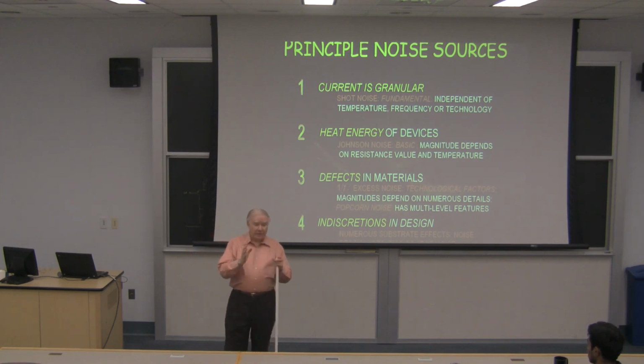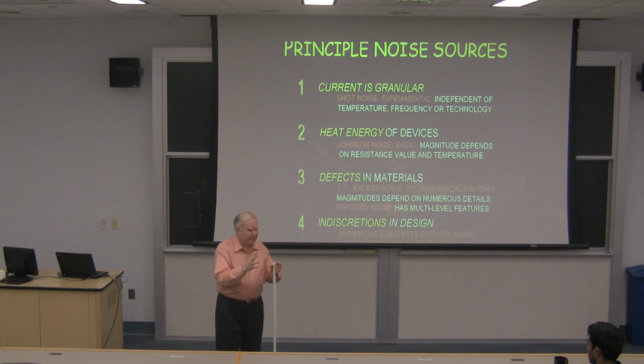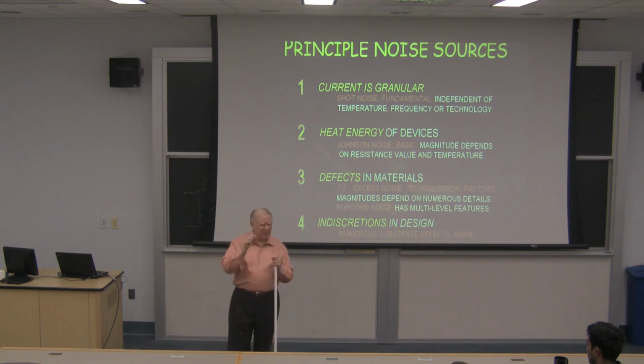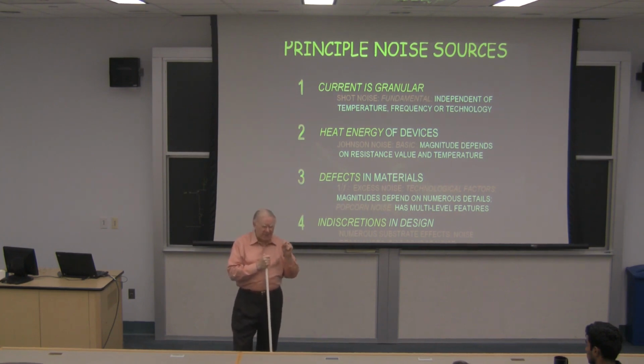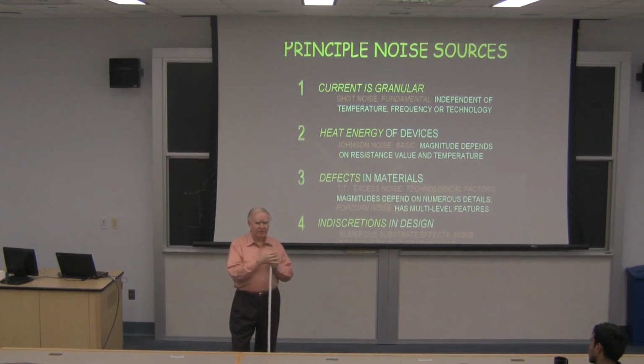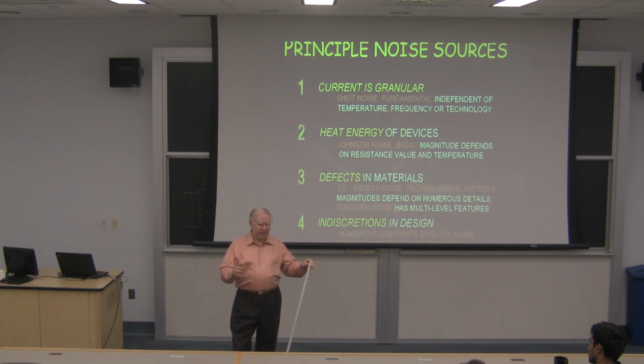Now, if in your circuit you see something a little bit funny at, let's say it's supposed to work up to 90, and at 100 degrees Celsius you see something funny going on, a little click in the response or a spike or something, you don't ignore it. You don't say, well, it's only going to work up to 90 degrees C. That's a little cry from the heart. The circuit is saying, I don't feel too well, and you attend to it right away. I mean, you must do that. I'm quite serious about this, because if you ignore little things like that, you'll have some nasty shocks when the product comes back from fab. So sweep generously over huge ranges. If you can, embed in your parameterization of your models the ability to sweep device parameters all over the place too.